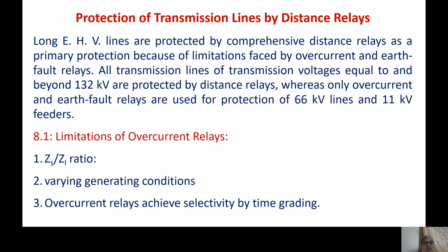We should do the reverse. The fault nearest to the source should be cleared the earliest. A fault near the load can be cleared later because that fault current is low. But we can't do that based on the principle of selectivity. Therefore, the major problem is time delay.